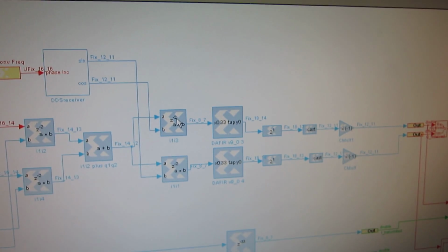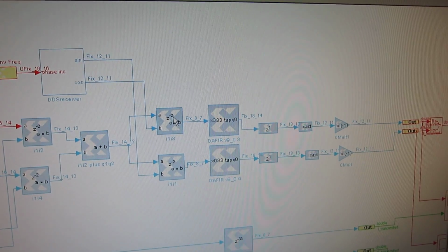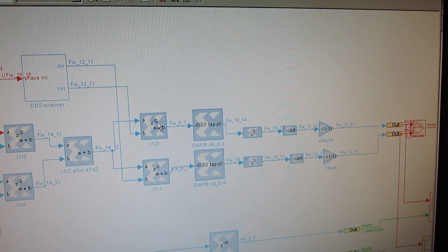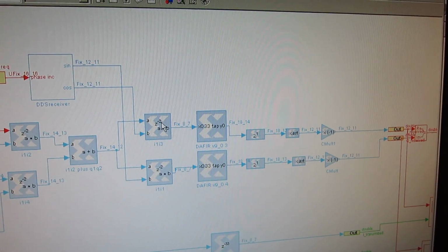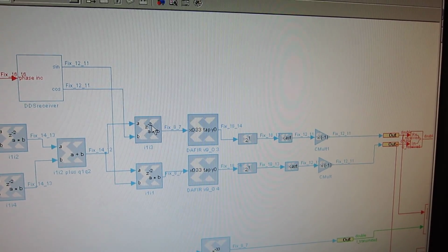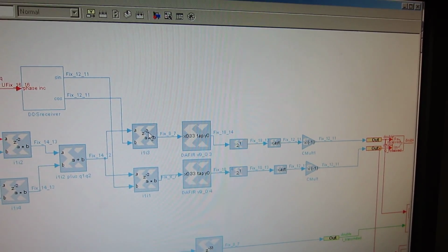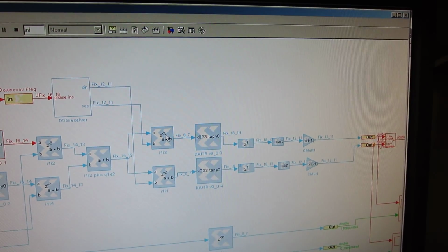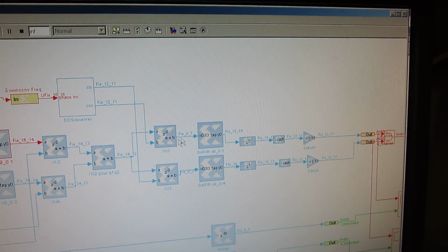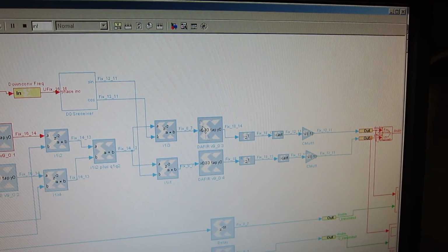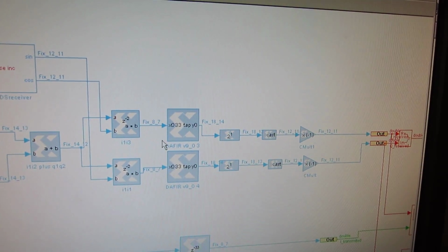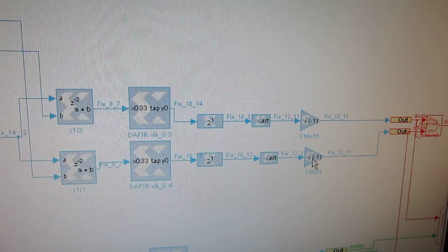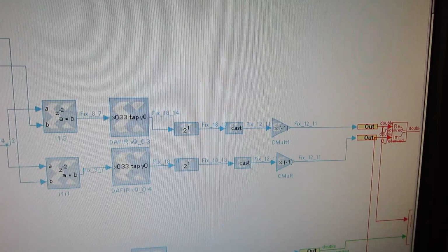If the local carrier frequency is the same, the signal can be easily recovered. In an actual implementation, the carrier frequencies may be slightly different. If this is the case, carrier correction hardware is needed, such as the phase lock loop. We have not implemented this for our project due to time limits. We then pass it through a matched square root raised cosine filter and downsample. We then output the recovered signal to the scatter plot.